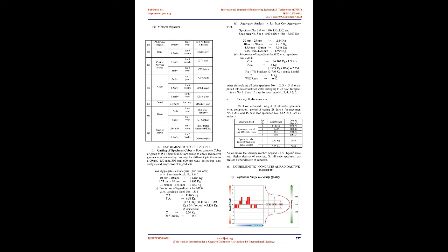The materials were placed in the mixer with a capacity of 56 dm3 in the following sequence. 1. Materials were initially dry mixed for 2 minutes. 2. Approximately 80% of the mixing water was added and then the mixer was started. 3. After 1.5 minutes of mixing, the rest of the mixing water was added to the running mixer in a gradual manner. 4. All batches were mixed for a total time of 5 minutes.